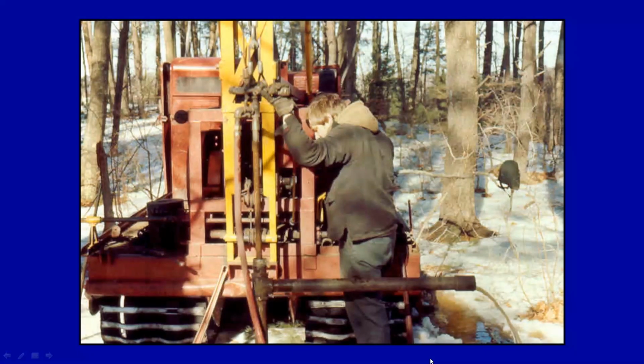Water is now jetted into the casing, which has an open bottom, to flush out the sediments that will lodge within the casing. That water comes out flushed and is dropped into a bucket where it is captured. It is graded for color, for transmissive capability, and for the coarseness and description of the sediments which are being flushed out.